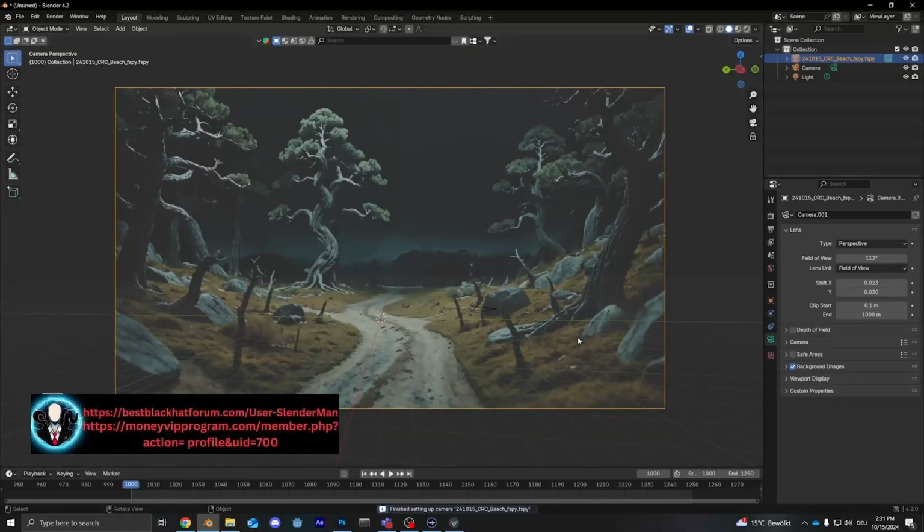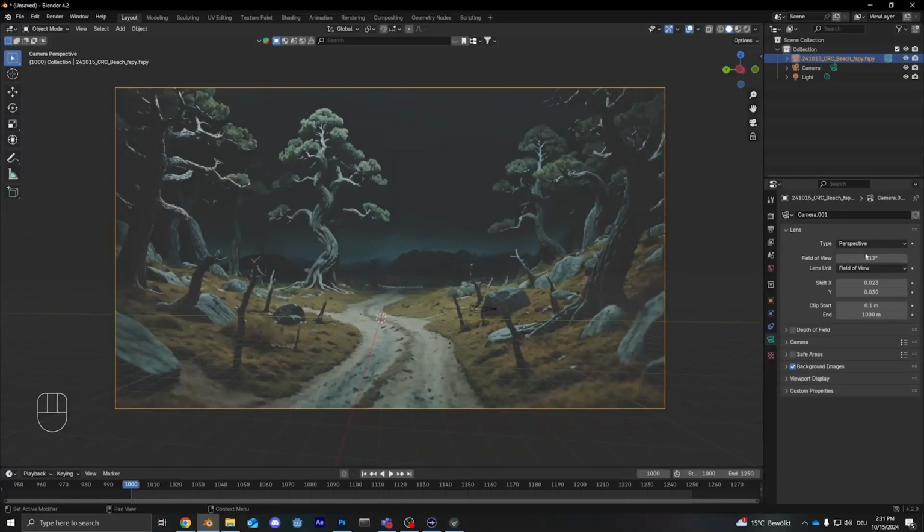And it's going to automatically import the image you gave fSpy as a background image and create a new camera with automatic settings. And you'll see this, it recognized a field of view of 112 degrees in the camera, which translates to 12 millimeters, which is an extremely wide lens. I suppose we prompted wide angles, so I'm not surprised. So what was all that about? Well, you can see that instead of us having to manually figure out all these settings, it already positioned this scene in a way that it fits into the Blender viewport.